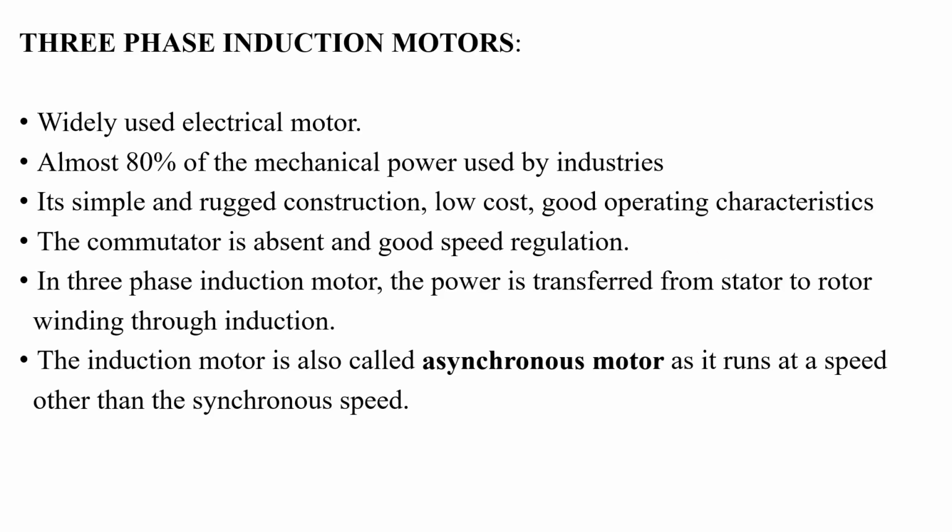In this video, we are going to see the construction of three-phase induction motors. We know that induction motors are widely used in industries. Almost 80% of the mechanical power is used by the industries. The construction of an induction motor is very simple when compared with DC generators or that kind of electrical machines. The operating cost is low, the characteristics are good, and the commutator is absent, so the speed regulation is very good.